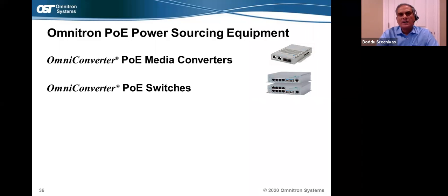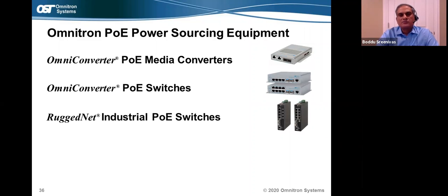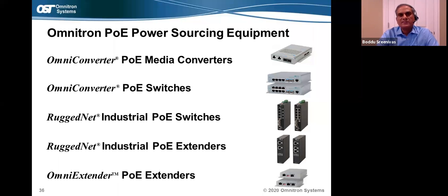Sure. So just like with the NID products, we have a pretty wide portfolio of power over Ethernet products, all the way from unmanaged PoE media converters at the lowest end to enterprise-grade PoE switches, 8-port and 4-port PoE switches, managed and unmanaged. And we also have a wide portfolio of PoE extenders. What the PoE extenders allow you to do is to extend the reach beyond the 100-meter limitation that you normally have with the RJ45 interface.